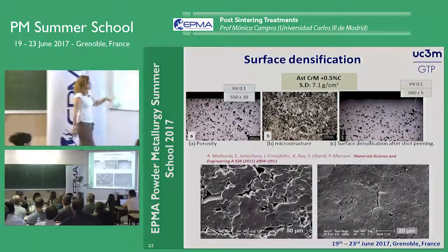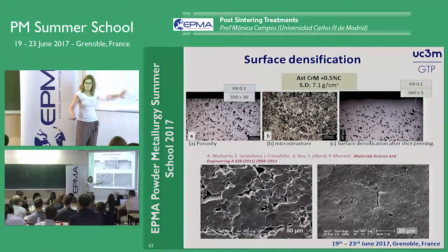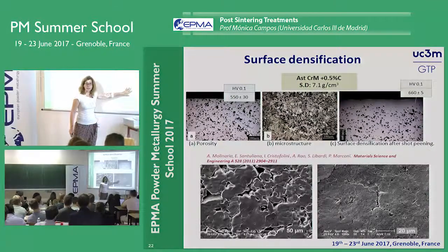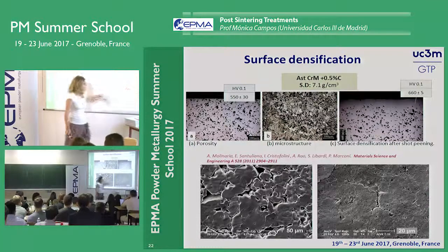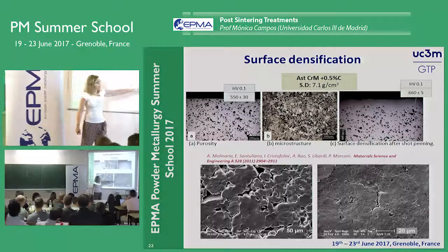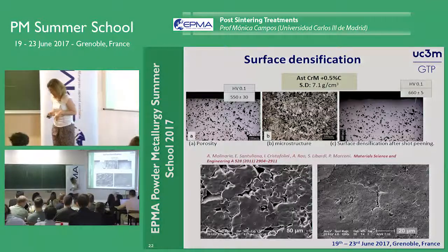Here is the difference. This is the sintered surface. We can see the same micrograph just after the shot peening process. This is the open porosity, and look here how this open porosity is totally closed.